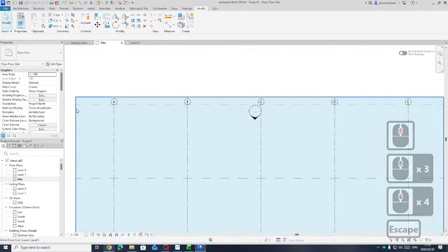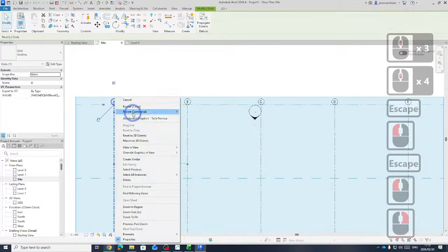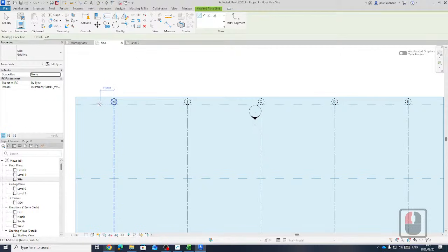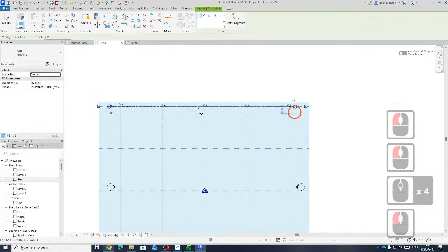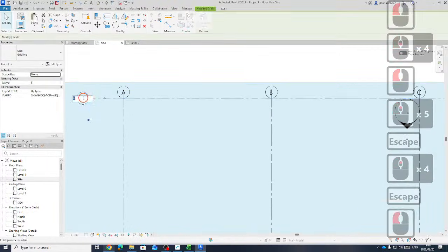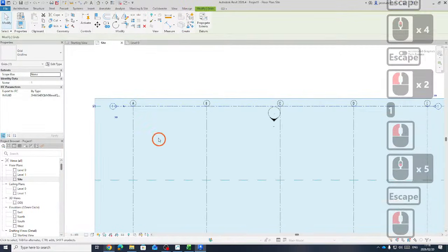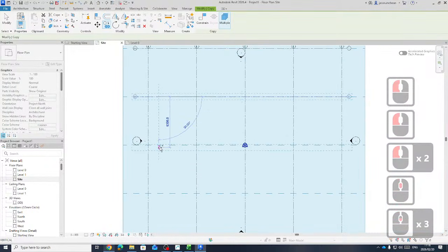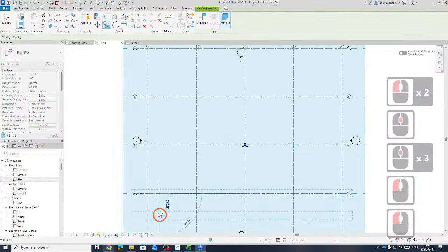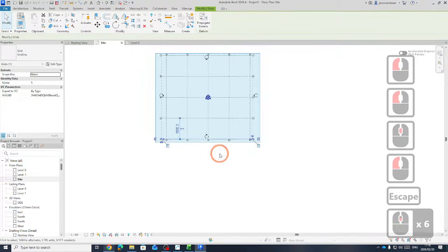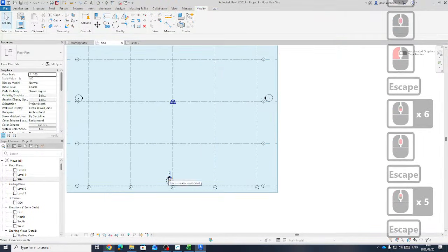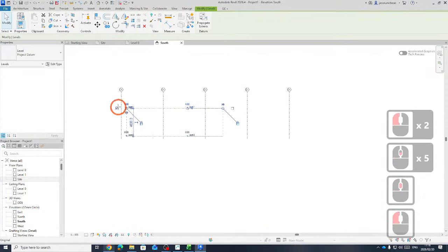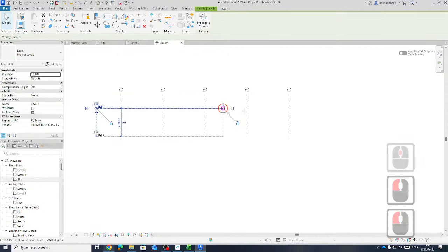So now I'm going to right-click, create similar. Now, I'm going to draw one grid again, and I'm going to change that to a number. And then I'm just going to copy these down. So the next stage is going to be the biggest difference between Revit and ArchiCAD, which is families. For now, straight, easy. If you go to your views now, you should start seeing a very basic grid system unfolding.